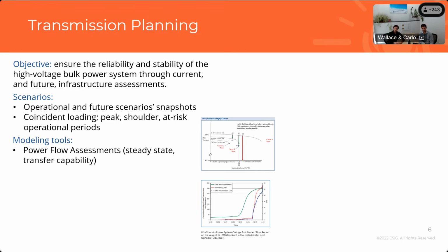We'll use this to do steady state contingency analysis, whether single component loss, cascading component loss, where you'll be looking at the follow-on effects of loading based on initial losses, or you might be looking at sequential contingencies, where you're considering first perhaps the loss of a generation asset, and then later on you want to look at a tranche of high voltage lines and see what happens if there's a near coincident loss of those assets. Those help us uncover the potential for cascading failures in our system, which is what we see in that image on the bottom there.